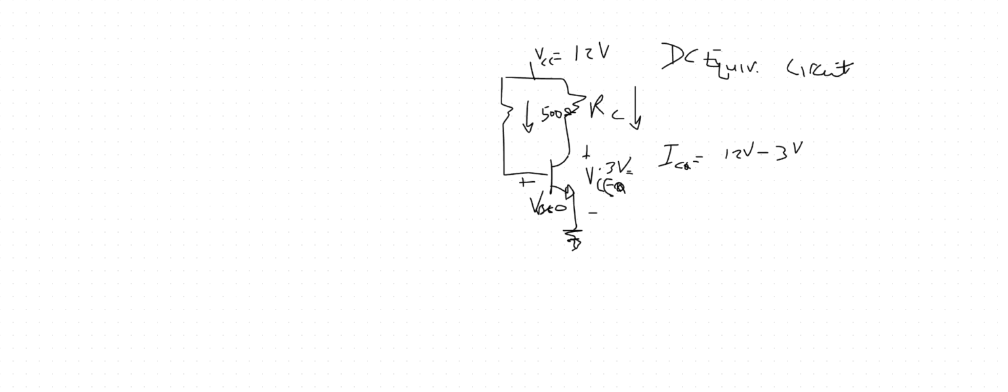Yeah, makes sense. 12 volts is at the source minus the 3 volts across here and ground, and then divided by the 500 ohm, right? So that works out to be what? 0.018 amps. Is it amps, right? Yeah.